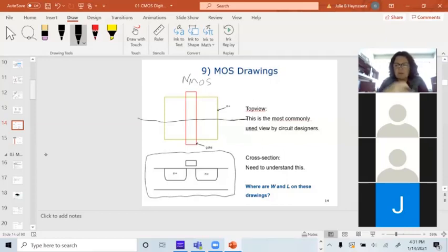And the side view image, the cross section, contains things like, oh, I can see how deep this N+ diffusion is going. And the different materials have slightly different shades of gray on the black and white, and you just kind of learn how to read that. The poly has a slightly different shade of gray, and the oxide looks a little bit different too. And you can start to distinguish these features and figure out what's going on. By the time we get to lab 4, I'm going to give you a drawing like this, and I'm going to ask you to draw the cross section. That's week 1 of lab 4. We're not going to get there yet.